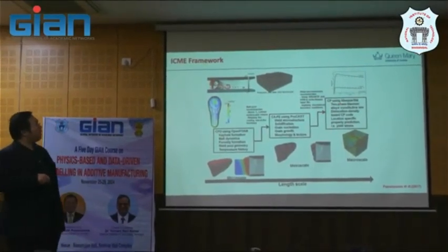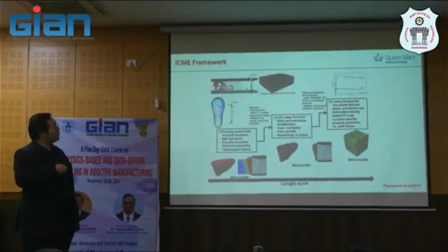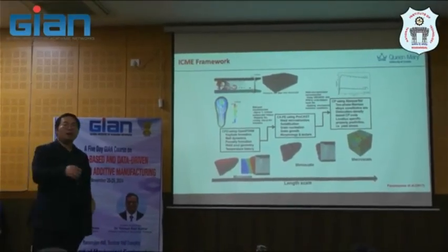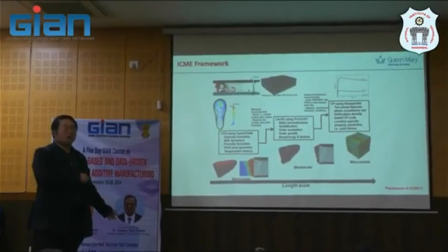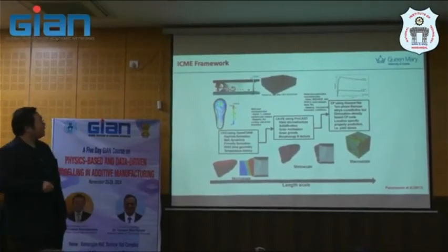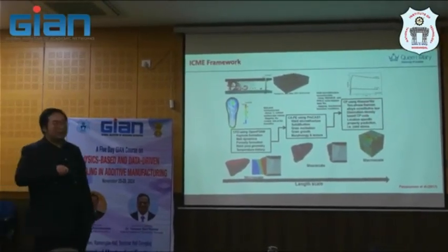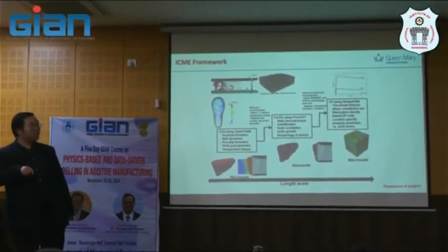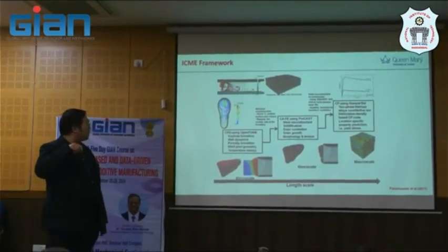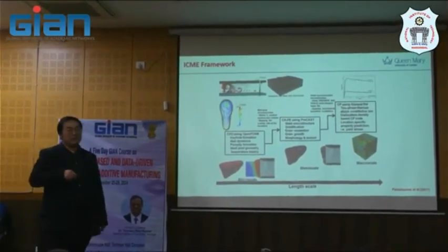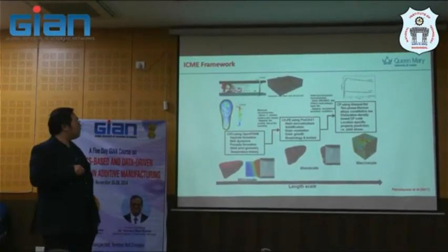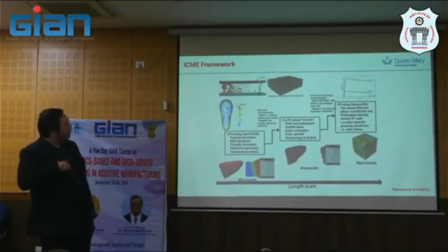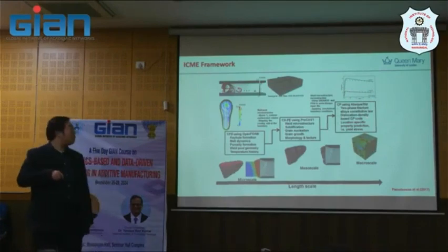And then we apply the mechanical boundary condition, which is derived from the melt pool calculation, onto the boundary here. And then in the next step, we use Abaqus with a user-defined subroutine to simulate the two-phase titanium constitutive law, using a dislocation density-based crystal plasticity code to predict the location-specific property, such as the static yield stress here.